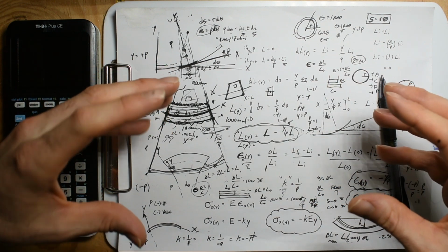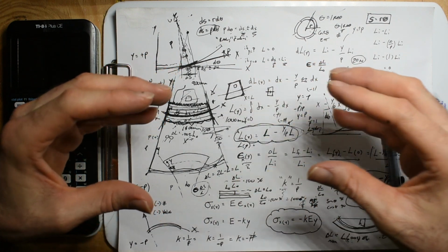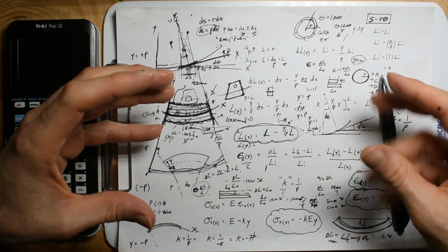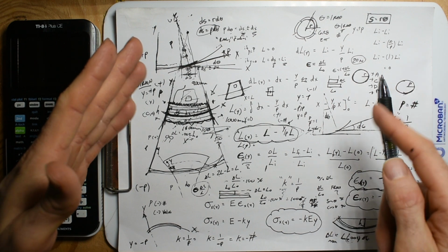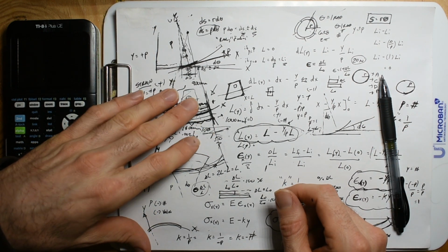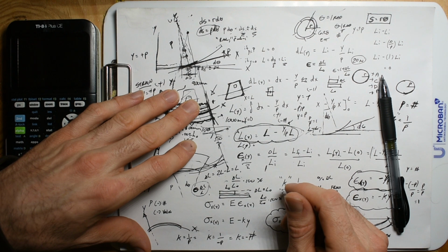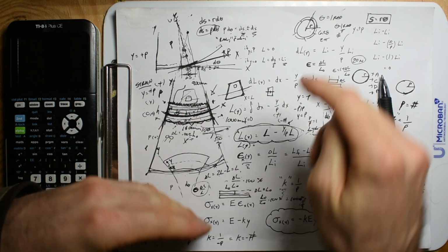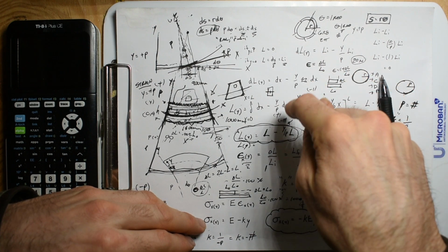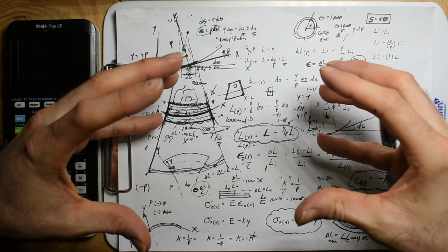And so then the reverse is true. If I only stretch the steel bar by some means, using force, and I can measure that I stretched it 1 millimeter, that means that I put half of 58,000, or 29,000 pounds, on it. So I can say that a change in length matches a given PSI.